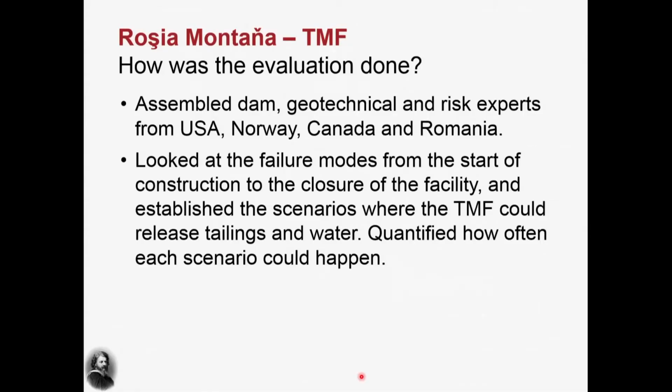We look at all the plausible ones, but you realize that for the terror part, we put a very low probability of occurring. The evaluation was done by assembling dam specialists, geotechnical engineers, and risk experts from different countries. And then we look at all these failure modes from the start of the construction during the entire lifetime of the facility, which the construction lasts about 12 years, and then the deposit, so the life was 25 years. Then after that, there was a covering and a renovation of the entire area.